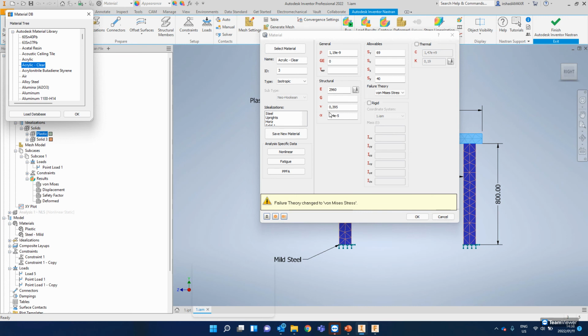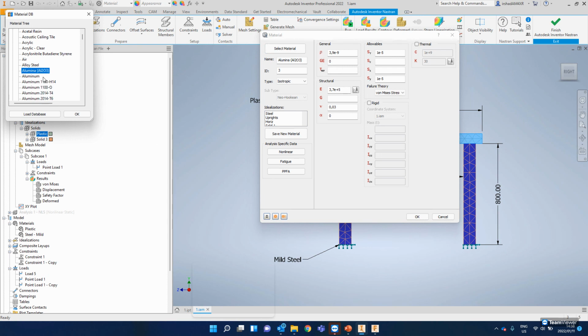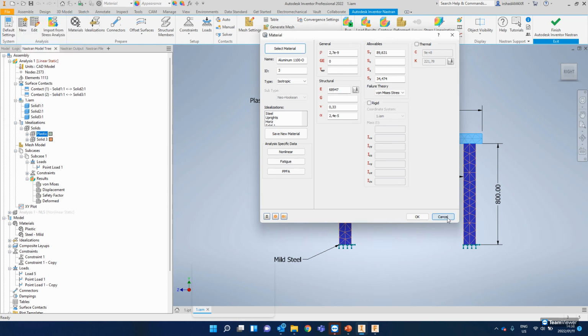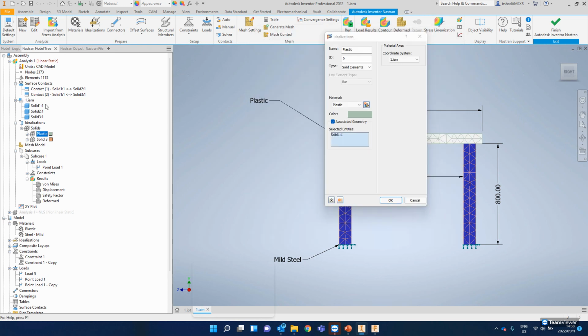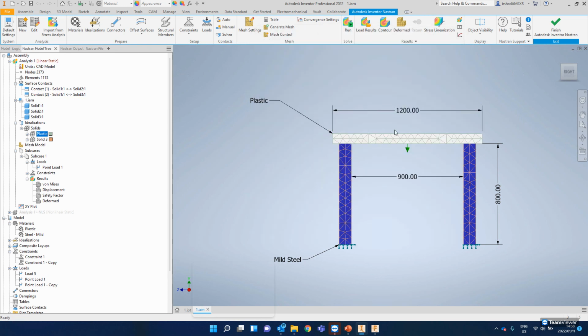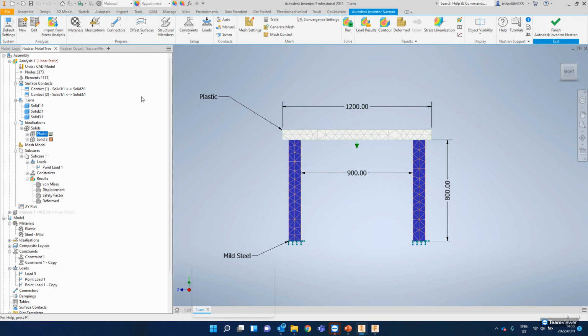In particular, we can look at Poisson's ratio and the allowable stress. So the maximum allowable stresses, then the yield stress, and all of those kind of things. So we'll find density, maximum yield stress, etc. So if I know that the maximum allowable stress is going to be reached in my analysis, then I know that the geometry is going to be changed a lot, and I'm going to need to run a nonlinear analysis. Otherwise, you can simply do this using Inventor's stress analysis tools.